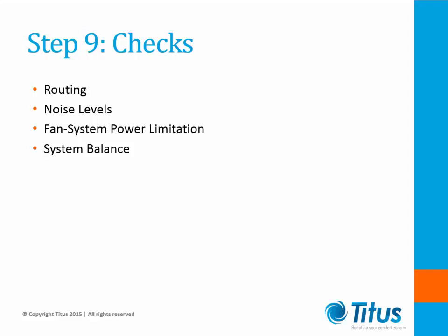When system resistance is calculated, a fan selection can be made. Make sure to include pressure drop for filters and any intake louvers. Both the supply and the return air pass all the way back to the equipment.